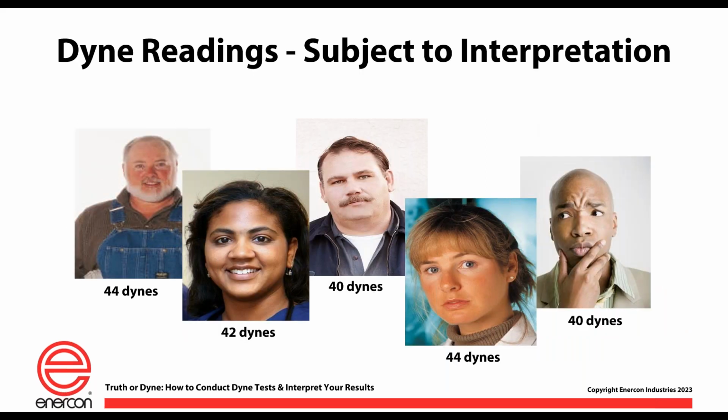And then, like all these test methods, you're going to see this repeated throughout the presentation today, it's subject to interpretation. Now, I can tell you guys, I can have three senior Enercon people in the lab, myself and two other guys. We can all do a Dyne test, particularly with a pen, stand there and look at it and not necessarily come up with the same number. And, you know, we have years of experience doing this. And the reason for it is simple. The test method isn't great.